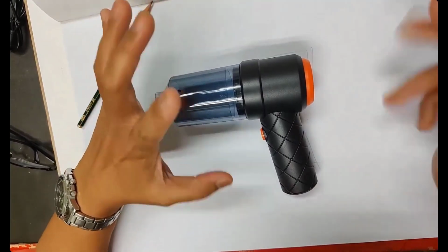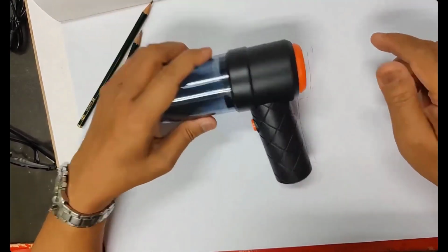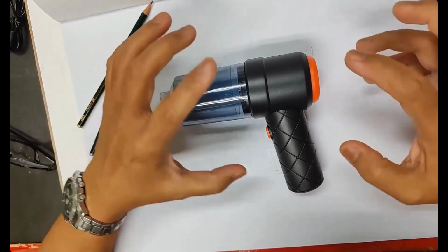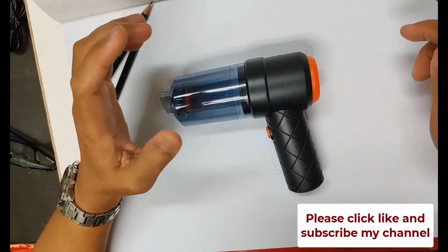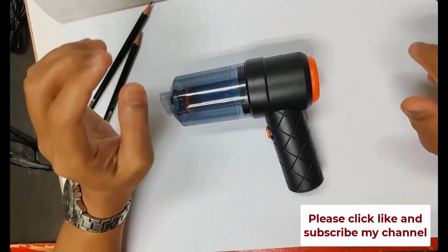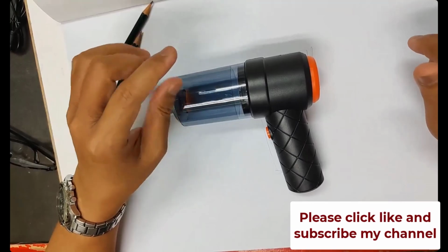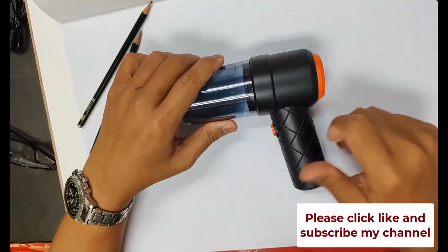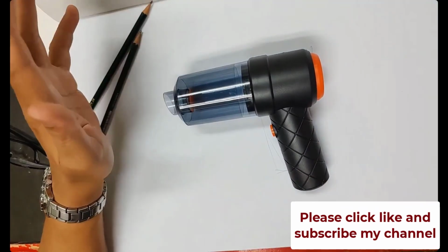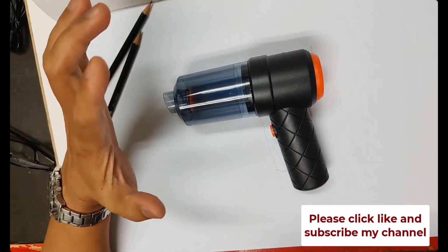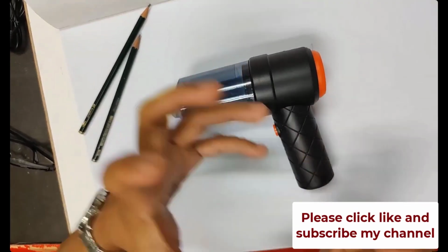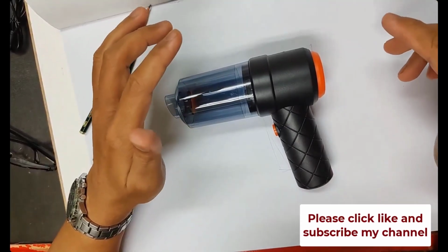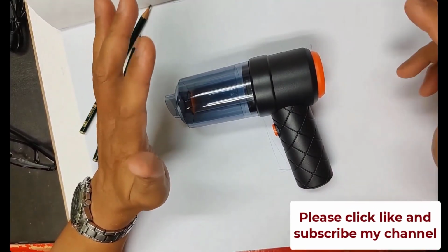Sometimes when we do product modeling in Solidworks, we start on paper, we do some sketch, then we take a little bit of dimension. You can start on the rough modeling first, and then in your part modeling in Solidworks, you can split it part by part. If you watch my previous video, that is how I do it. I do the whole main body modeling, then I split it into front casing, rear casing, or top casing.